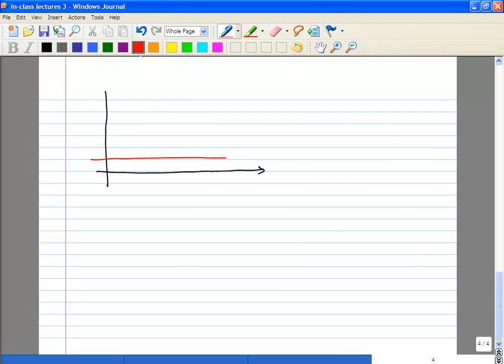So let us say the output noise looks like this. So this is your output noise floor. Okay, so let me also draw here. We know that noise goes from 2FLO and 4FLO and so on, right? That's the rate of the switching.